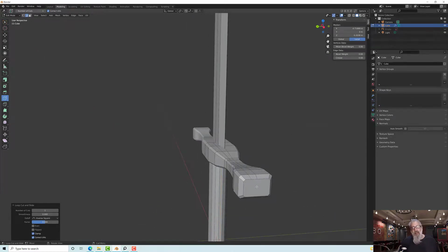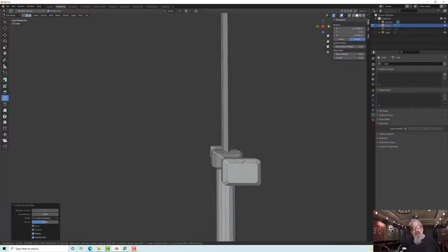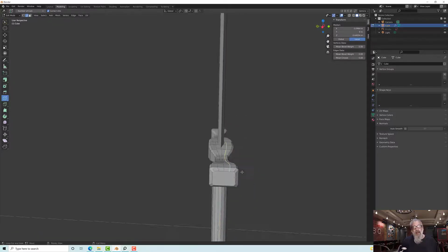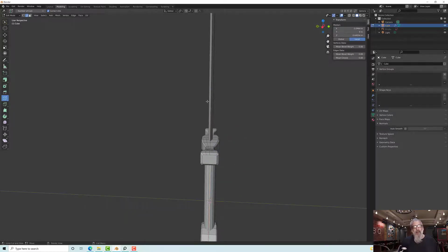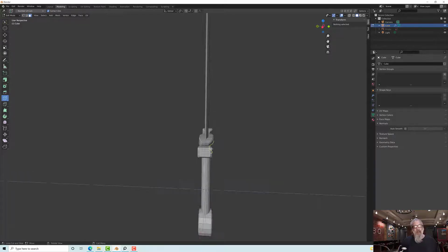Because we've got an end gun on this end, I need to join those up. So let's go and use the knife tool. I'll use K and then just grab that and pop it underneath, and then press enter. There we go. So now I can delete half my mesh, and I'm going to delete this half, and this might be a little bit tricky in terms of selection, so let's do this bit by bit.